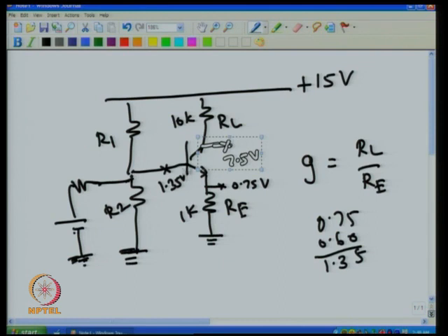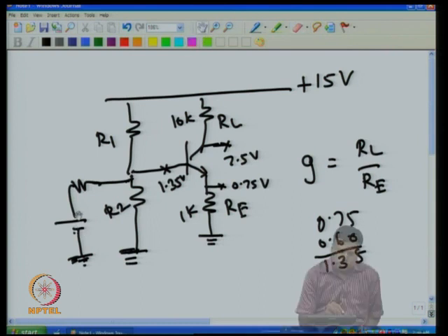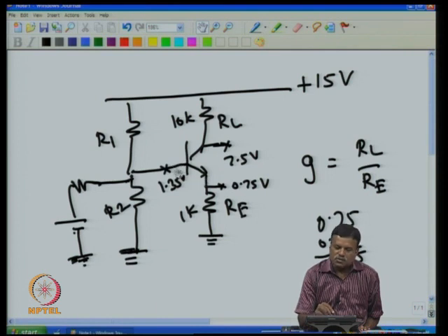one problem with this is that if I give this and get the amplified voltage at this point, this change in voltage represents the change in voltage here. That is, if this voltage changes, I know that this DC voltage also will change. But unfortunately, the change taking place at this point is not necessarily due to this alone. This voltage will change even when the base emitter voltage of this changes, and the base emitter voltage will change when the temperature of this transistor changes.